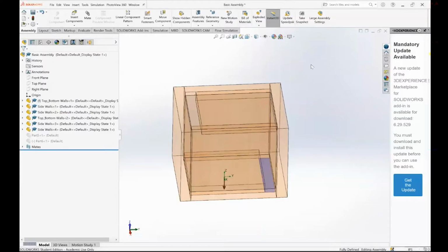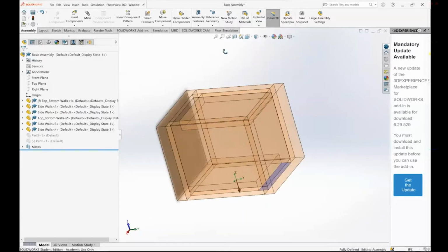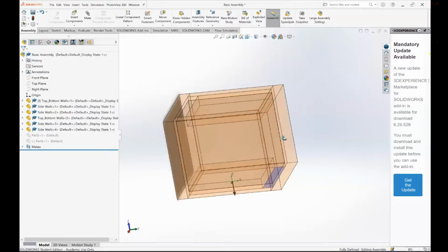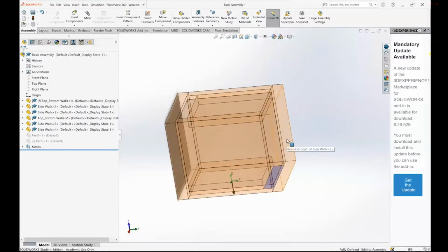For our project, we use the SolidWorks flow simulation add-in. Specifically, we're going to go over free convection or natural convection of a solid body. The very first thing you're going to need to do is create your body. I did mine in an assembly, and it could be either a tube or a cube or any solid body.